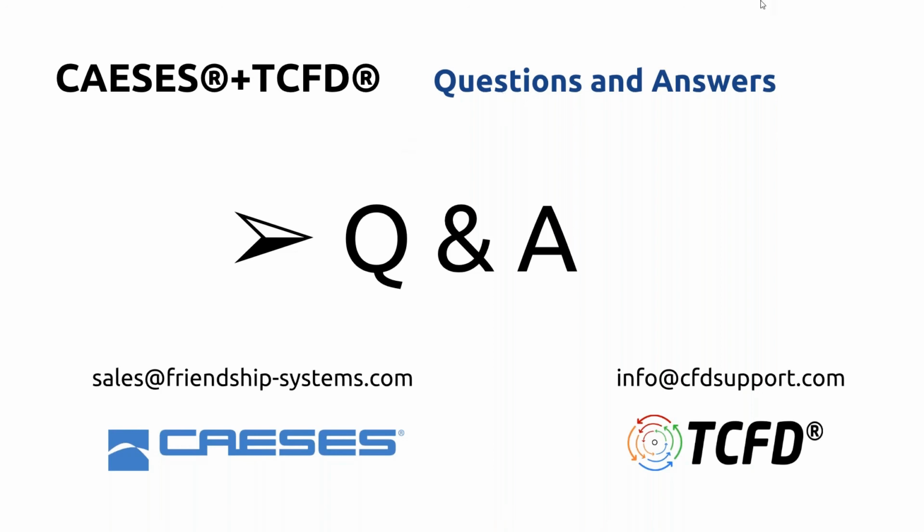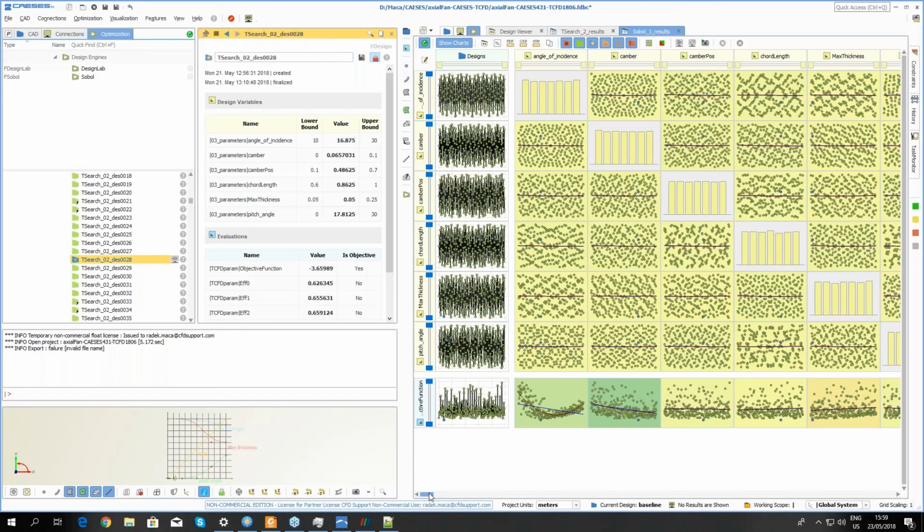Maybe I can take something again. I see there are two related questions from the same person. Brian asked about the method used for the design of experiment in this case. So in this case, we used the Sobol algorithm, or Sobol sequence, to run the design of experiments. You can look up the details, but it's a low discrepancy sequence that tries to cover the design space as uniformly as possible.